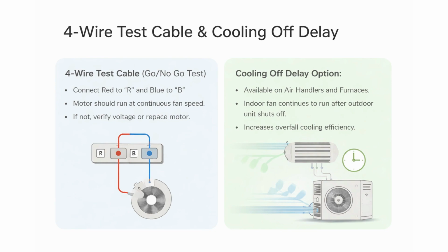Another feature to note on these systems is the cooling off delay option. This utilizes an electronic time delay relay to keep the indoor blower running briefly after the outdoor condenser shuts off, which extracts the last bit of cooling from the evaporator coil.